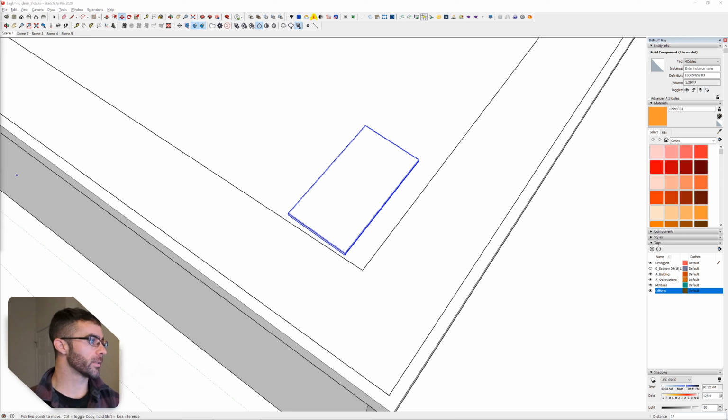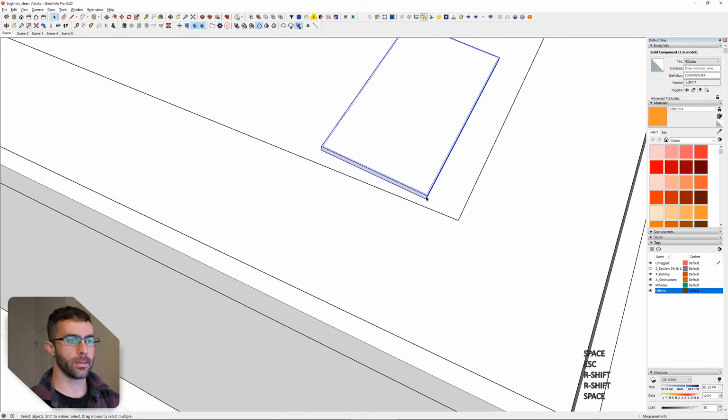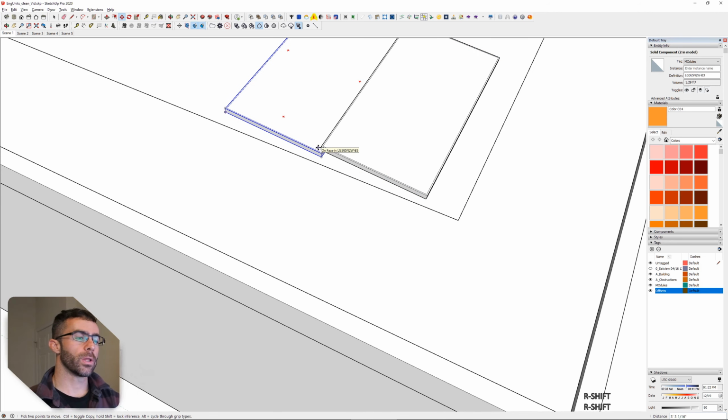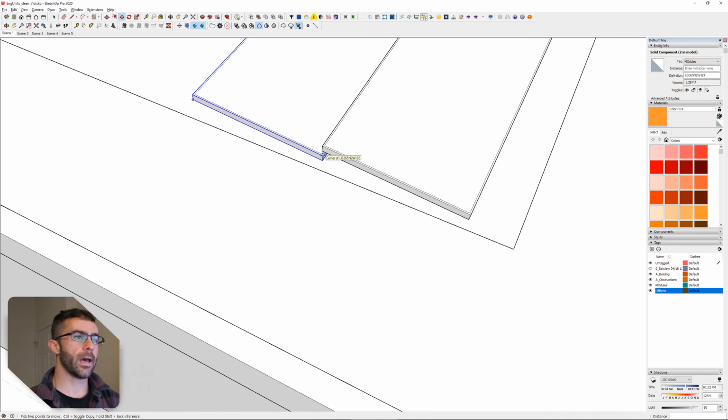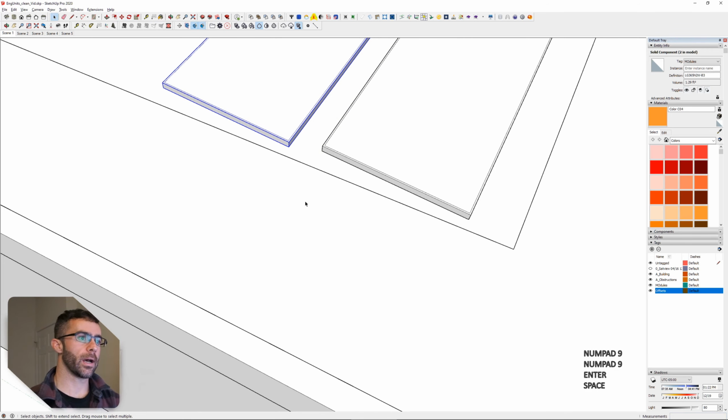So if we go back to that consideration of inter-row spacing being 9.9 inches, we know that we need to add a new module that is 9.9 inches away from this one. M for move command. I'm going to move, tap control to toggle the copy function of the move command. We line these two modules up, and then I add 9.9 inches. That's the easiest way I've found.